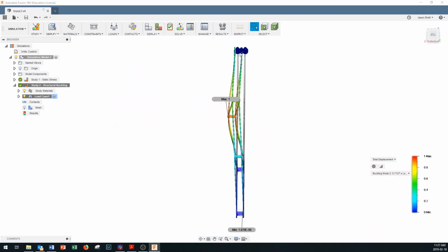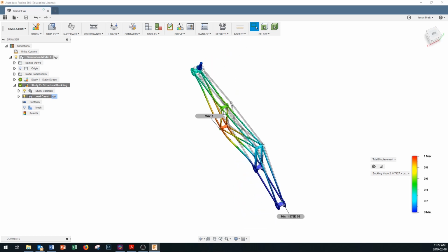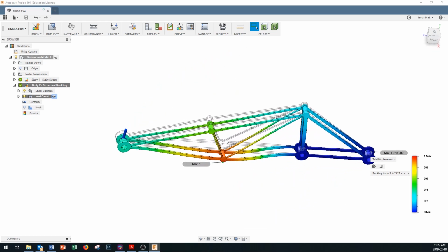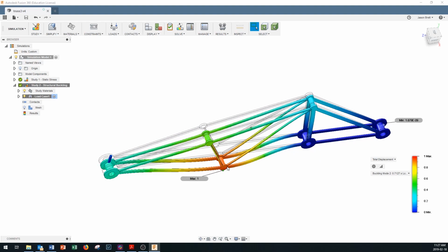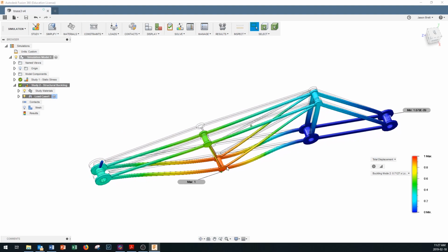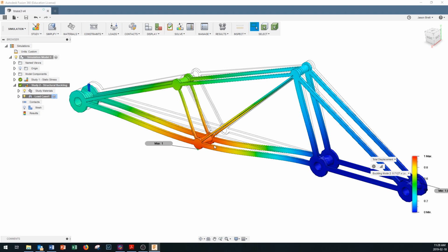And you can see that with this design right here, we've got buckling occurring right in here. We put that load down there. We get a compressive stress occurring on the bottom. And these nodes right here are a little bit too long and they pop out to the side. We're getting pretty close, but let's go back to our